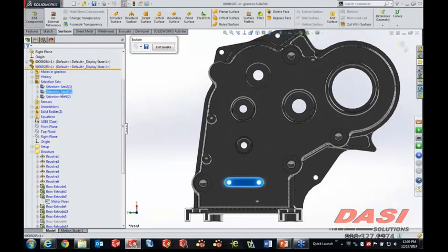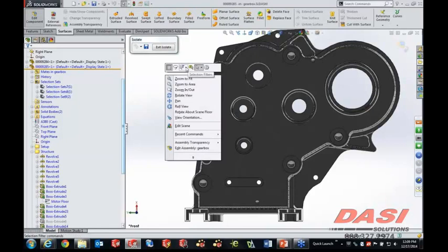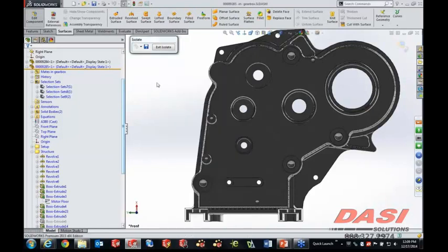And by clicking on these different things, you're going to see a pre-grouped selection set. So in this case, we might have been picking these faces as a precursor or setting us up for simulation, maybe adding loads and restraints. This one over here, I just clicked and showed you how to do it. But we'll do this in assemblies later and any other place that you would do a multi-select that maybe you only want to do once and never have to actually do again. Selection sets are something we borrowed from one of our sister products, SolidWorks Composer. So pretty cool thing. All right, let me get out of this face filter tool for a minute.